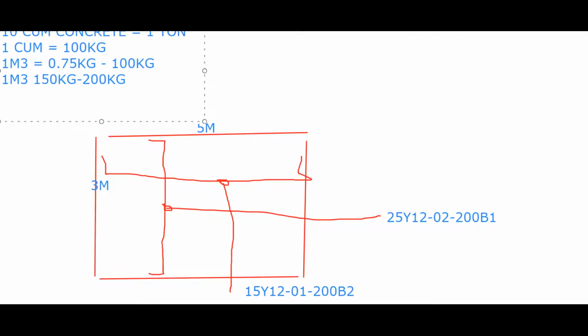Then this shape we are drawing here is to guide you. It will help you come about this. For instance, the bend here is 0.19, the bend here is 0.16, and the clear length is 750. So 750 plus the right bend plus the left bend. If I go to a different one, it's still the same thing. So let me go to one that will be a little bit different from these two.